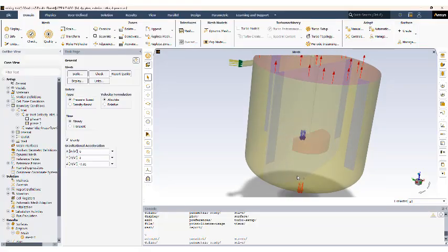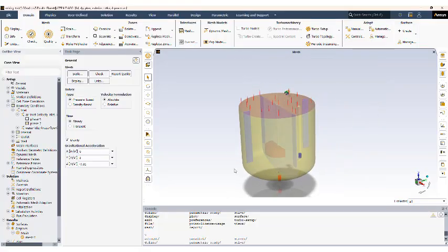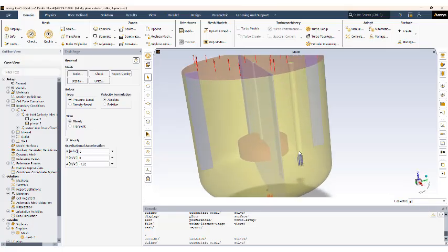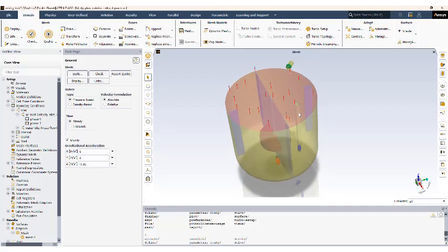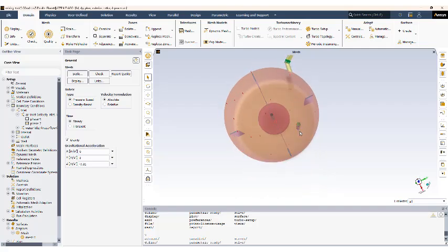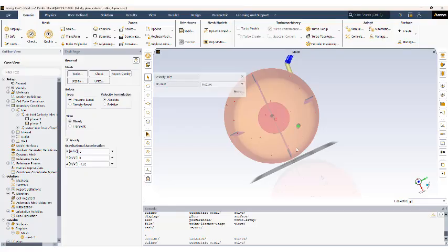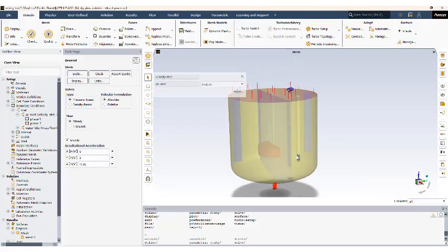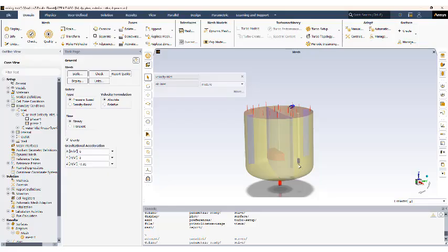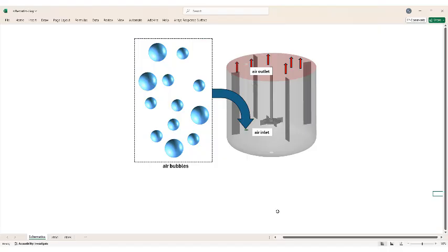domain. And we also have a stream of air, which is our population balance phase model. Air is injected at this inlet down in the bottom, close to the impeller. And then it's allowed to flow out of the system through the top of the domain. So I set the top of the domain as an outlet boundary condition as well. So this is what we have in this sketch, in this schematic, showing where air is added into the domain.